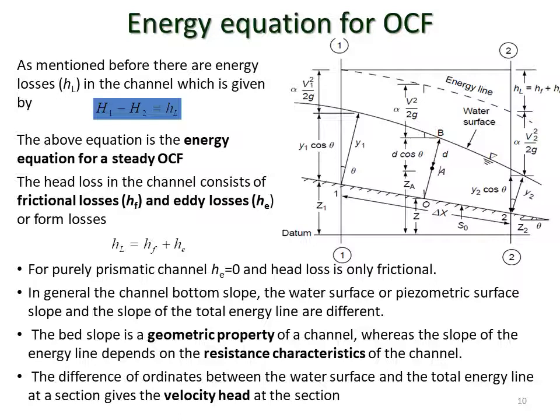Also note that the difference between the piezometric surface, that's the water surface for open channel flow, and the energy line gives you the velocity head of flow. So in the figure we can see that the difference of elevation of the energy line and that of the water surface gives you the dynamic head or the velocity head at any section. So that's pretty much about the energy equation for open channel.